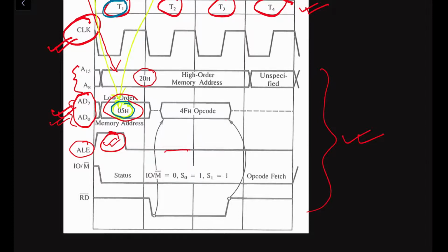So from the memory unit, whenever some data is transferred to the microprocessor, it is called a memory read operation. When we have a memory read operation, we have to enable the memory. So the memory part is an active low signal. Therefore, we have to keep this signal at the low position. You see, here we can see input output. This one is low.